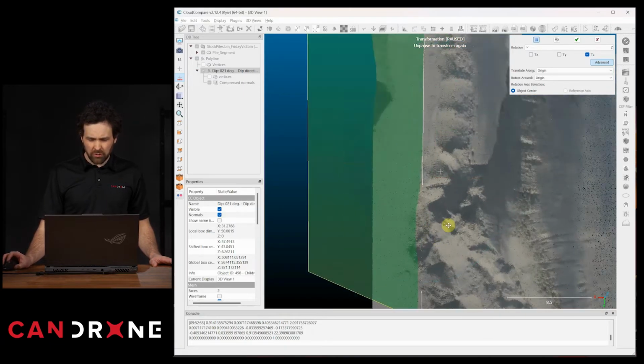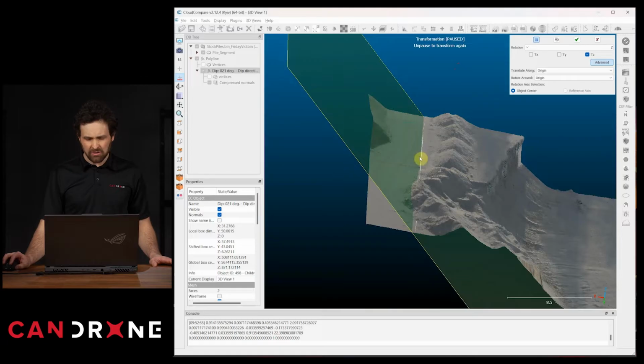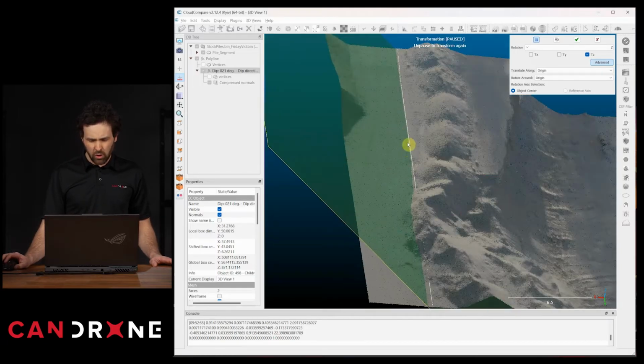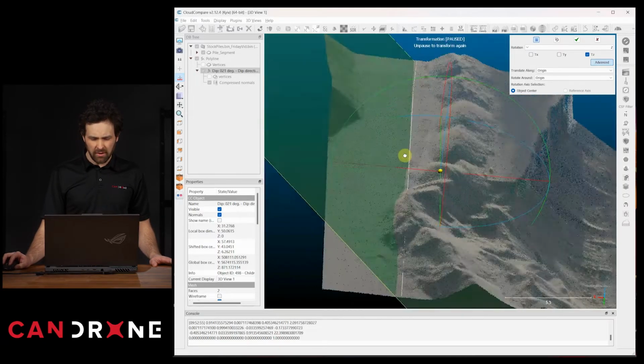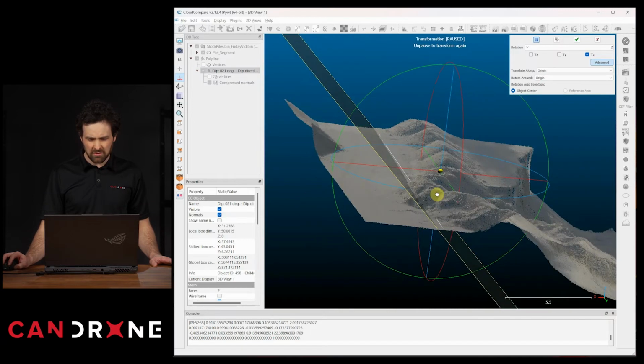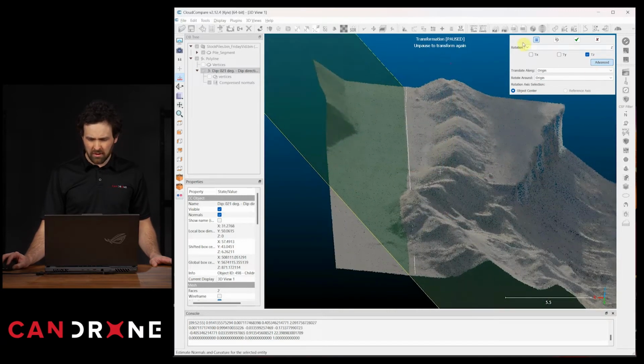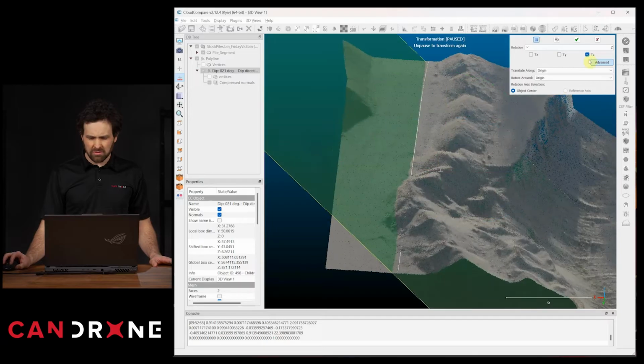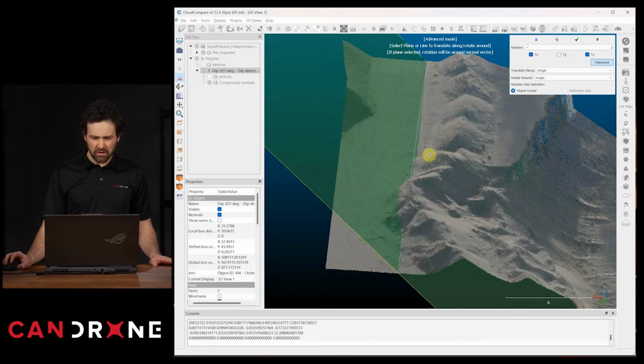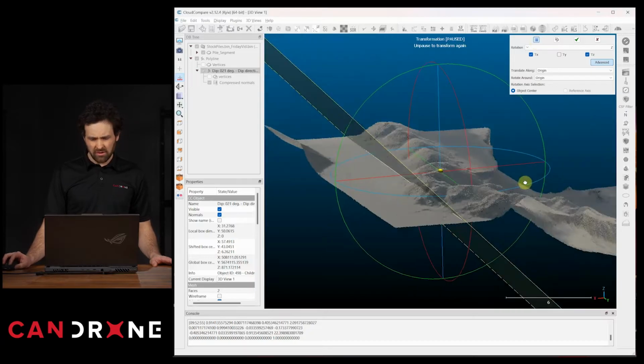So what am I doing? I'm looking at how this plane intersects the edge of the roadway with respect to that polyline that we first created as a reference. And I'm going to pull this back forward a little bit. So I'm going to unpause the tool and I'm going to re-engage this Translate by the X. And I'm pulling this along with the right click. So we're getting that to sort of sit snug against that reference polyline. And we're going to pause again, look around at that.